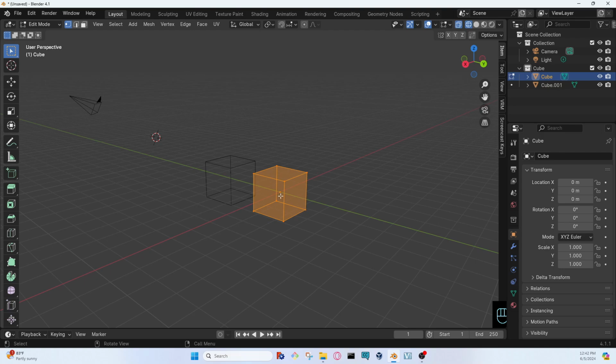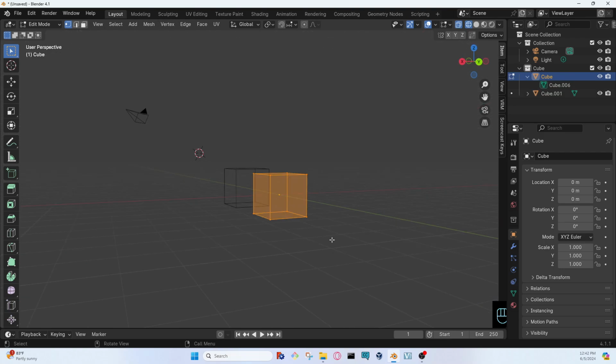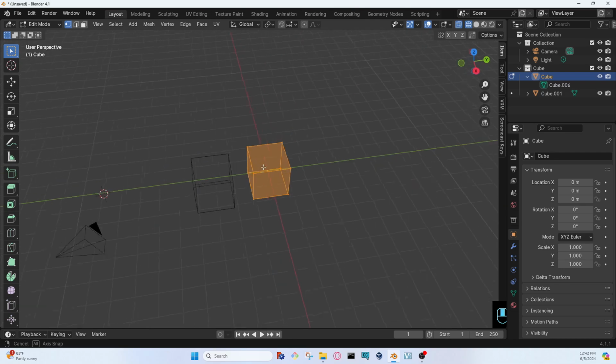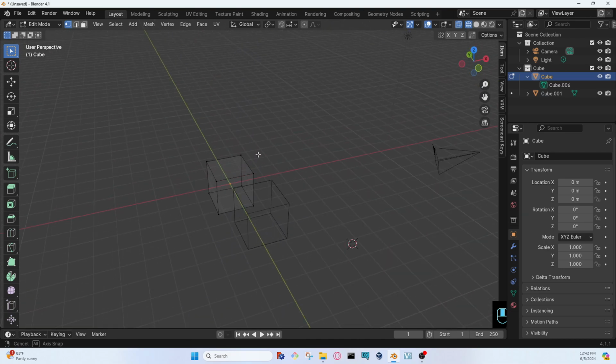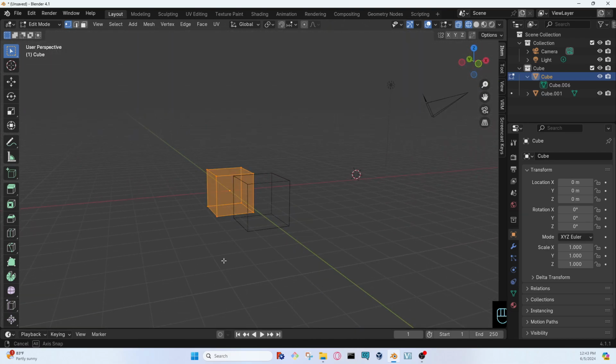However, if this box had multiple layers of mesh, like say we extruded it, added more faces, and did things to it, and it was still all the same object, everything would get selected, blasting all the way through across whatever plane you're going through. If I'm looking down the Z-axis, it'll go down all the Z-axis. If I'm looking down the Y-axis, it'll go down all the Y-axis. It'll select everything in X-ray mode that is behind it. So be careful with that.